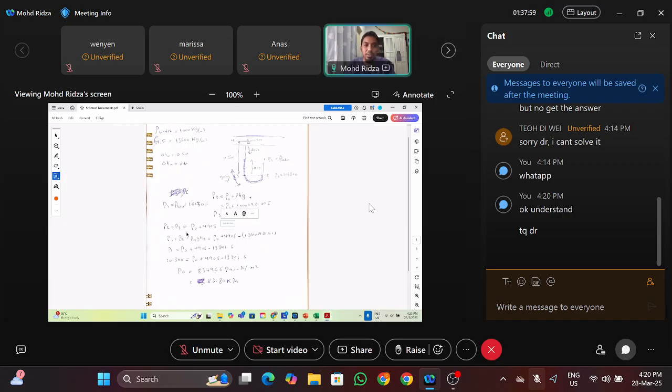Right. So okay, I see P2 equals P3 here. P2 equals P3 equals P0 plus 4905. Where do we get this? P0 plus. Okay, P3 equals P0 plus rho Hg. Where is your P0? When you use P0, you are assuming P0 is here, at P4, plus rho g h: rho 1000, 9.81, 0.5.